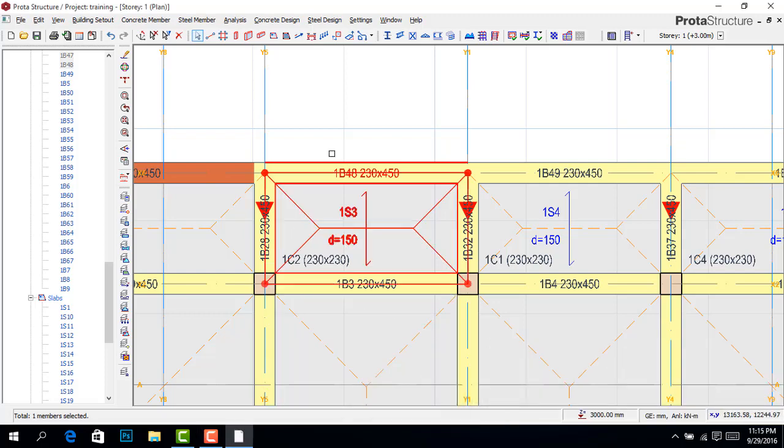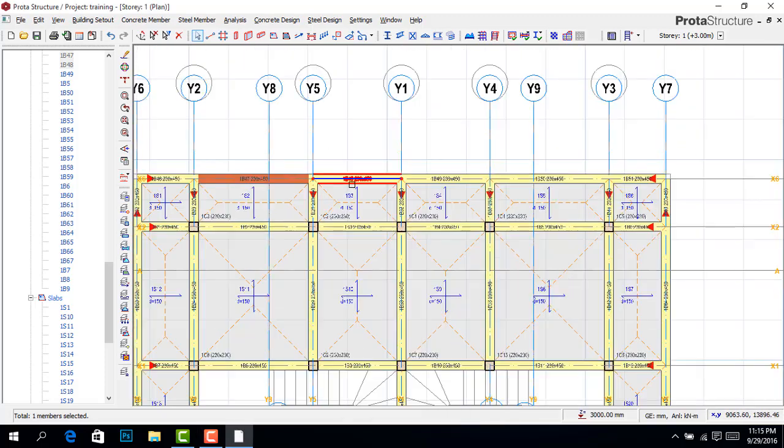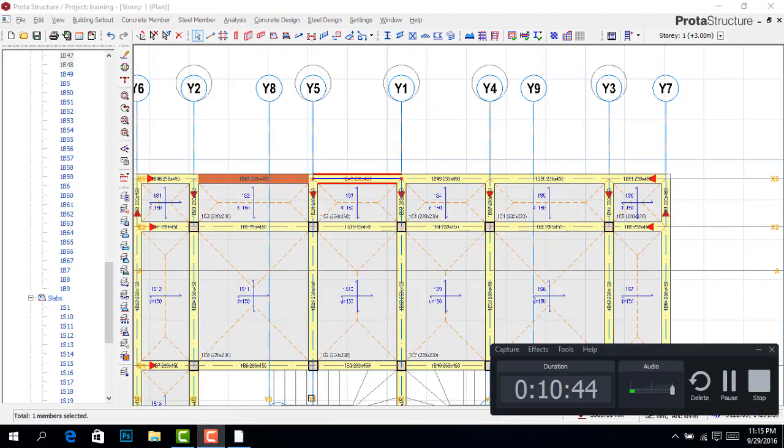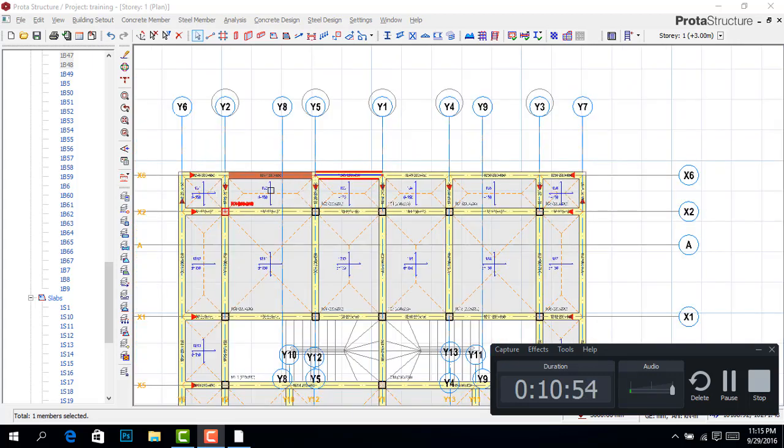For the purpose of this training, we'll just make it a bit snappy. But when you check the areas where the walls are, you copy and paste there. But there's a quicker way. You just click on a beam, hold your shift key, and click.